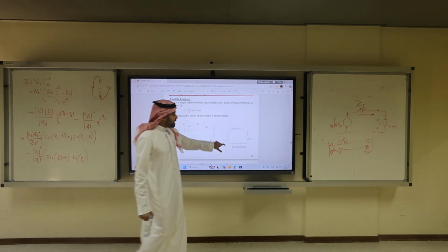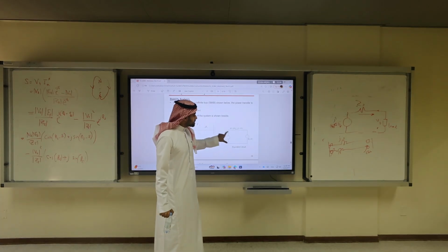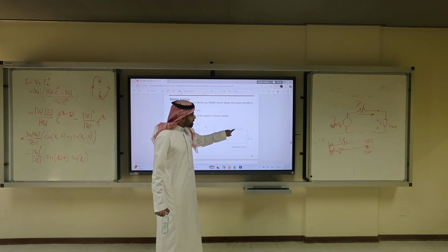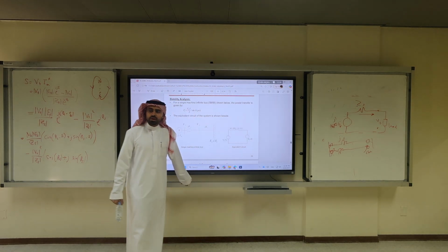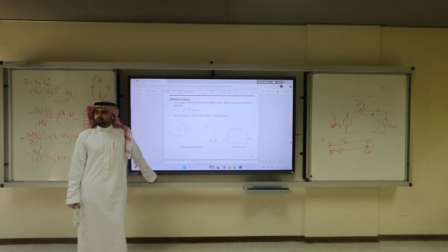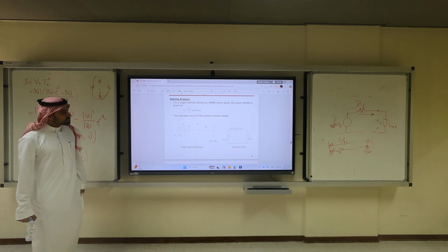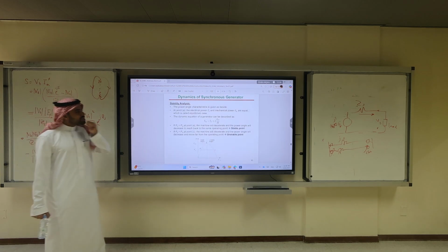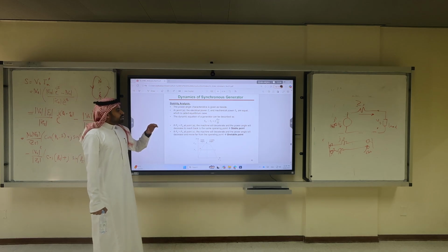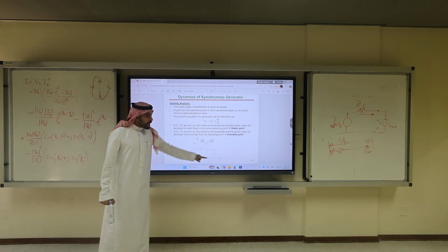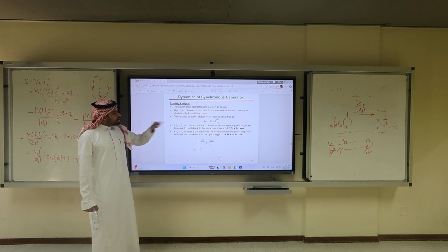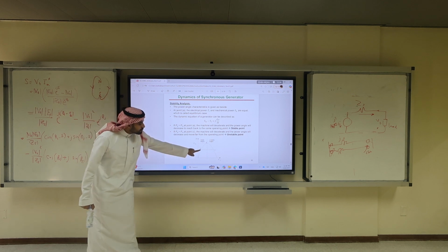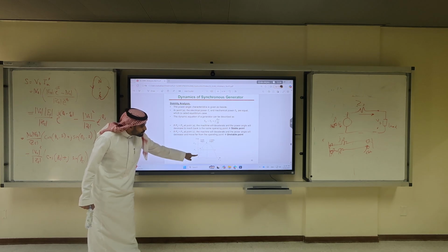If you draw the equivalent circuit, it's two generators. This is the infinite bus. This is the synchronous. And you sum all of the reactances. We ignore armature resistance. It turned out there is something with synchronous generator that's really important, this power angle characteristics. Let's look at point A. This point A, this is electrical power.